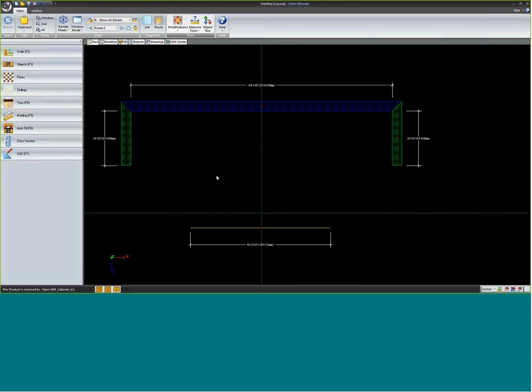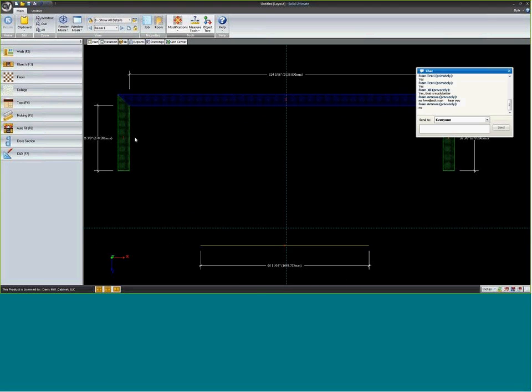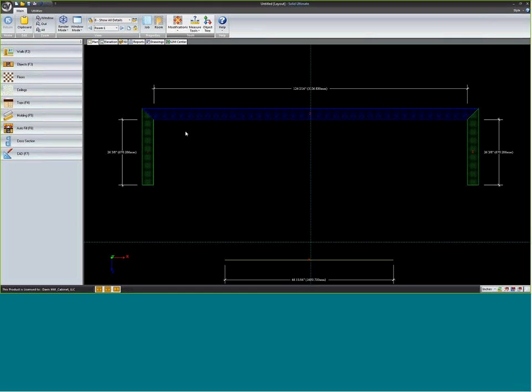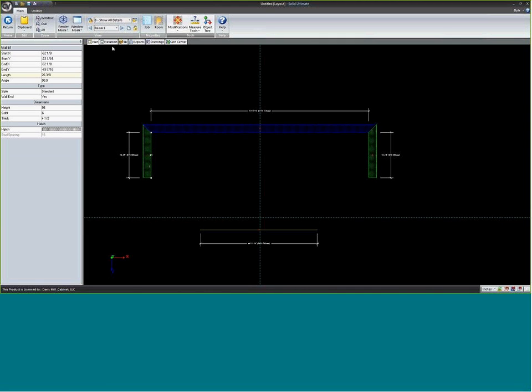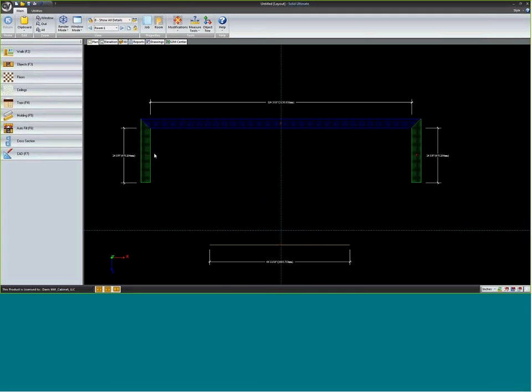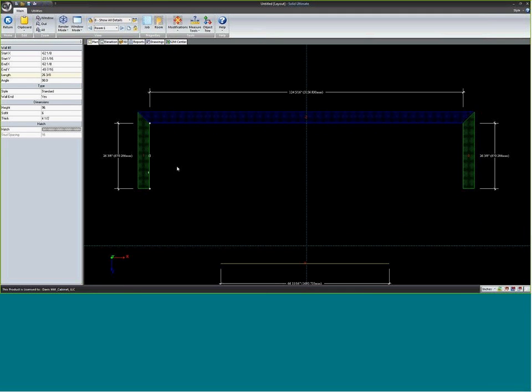Other than it turning the wall green, a wall end does two things. It will help prevent a cabinet from trying to attach to this wall. When I get a cabinet close to this corner, sometimes it wants to turn and attach to this wall. The other thing a wall end will do is when I go to my elevation views, it will bypass any wall ends, so you don't have to cycle through a bunch of blank walls that you don't really need to be looking at. So that's a wall end, and I would encourage using those whenever you can. It does make your drawings a little cleaner.